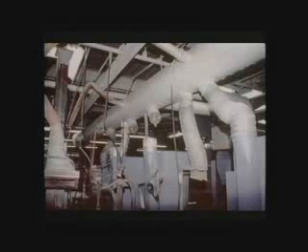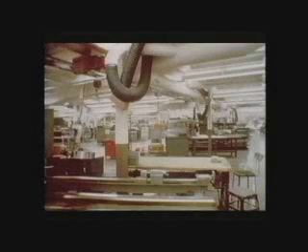When constant plugging of ducts is the problem, check the transport velocity. Is it adequate to prevent settling? If employees complain about the hood or refuse to use it, check to see if the hood interferes with work, or perhaps the hood just doesn't do the job of providing good emission control.